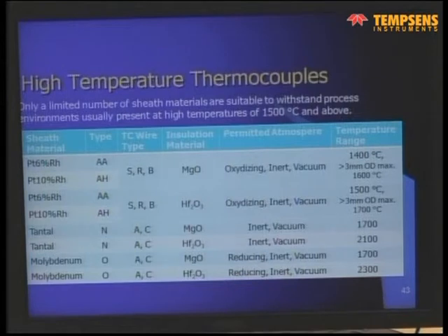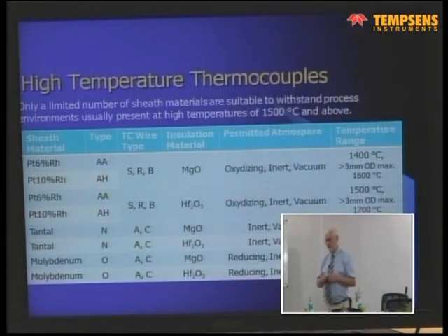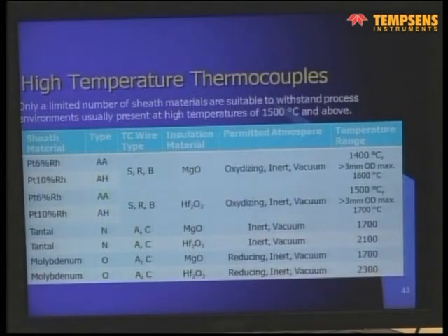Molten metals are extremely aggressive. Extremely. And it is not easy to do quite precise immersion measurements with thermocouples in molten metal. Even not at lower temperatures like lead or tin or zinc, which are quite reasonable temperatures. Even aluminium, 660 degrees, is not really a high temperature, but molten aluminium is extremely aggressive to steel protection tubes. So this is not possible.